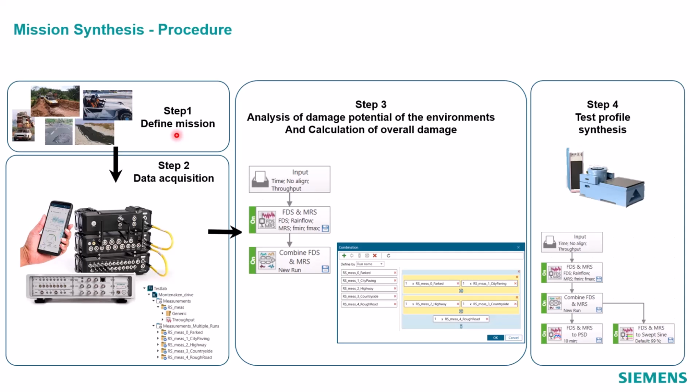In case of things like a dump truck, having actual debris or rocks or sand or whatever you're filling that truck in actually impact the bed of the truck and so on. And so these missions are making up the life cycle of the vibration environments that that component is going to see. And we want to capture that vibration environment by taking data for all of those missions.